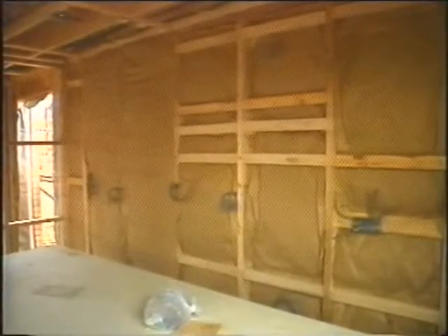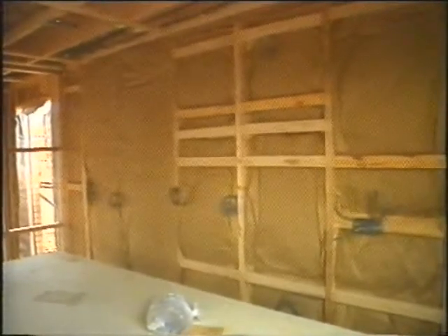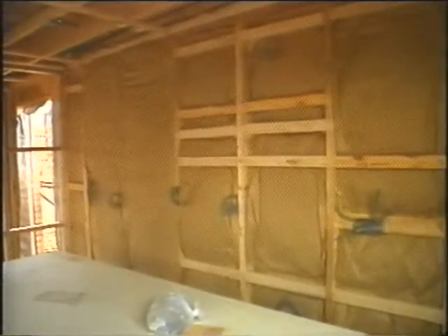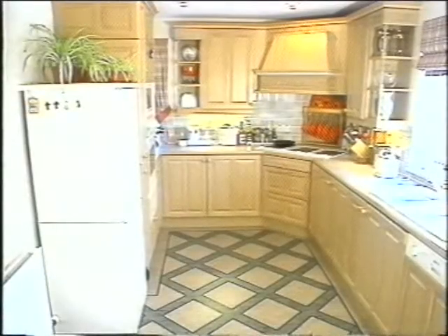If walls aren't insulated, up to 35% of heat can be lost through them. Cavity walls should be filled with an appropriate material. Floors can account for 15% of heat loss. Upstairs that doesn't matter because they let heat rise from below, but the ground floor may pose a problem.